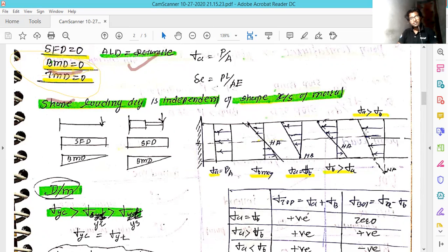And just to the right of that diagram, a different kind of loading is applied on the rod, which is a cantilever. The first notation, in rectangular form, denotes the axial forces. When you apply the forces, the axial forces will be distributed equally over the entire cross section. It is denoted by the arrows, and the length of the arrow will be the same for the entire cross section from top to bottom. So it denotes that the stresses in the entire cross section remain the same.